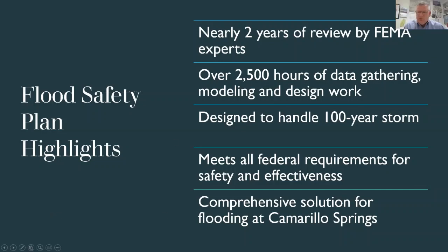And Ron, just a couple things to add on to that. That was a great summary. Yes, it was nearly 2 years of review with FEMA, and it is a very detailed review process. It's quite rigorous and is followed throughout the nation. It requires us as the engineer of record to go back to the very beginning, look at the watershed, and determine flow rates, and then compare those to what FEMA has published in flood insurance studies for each of these watersheds where they have mapping.